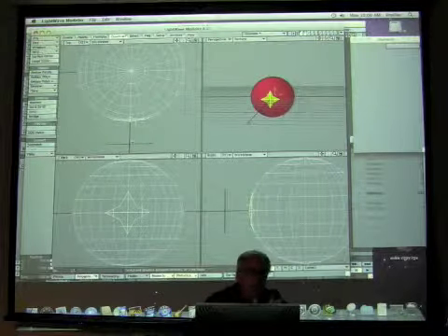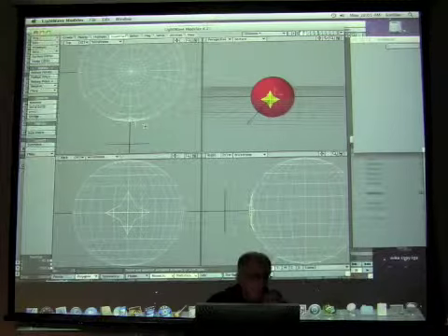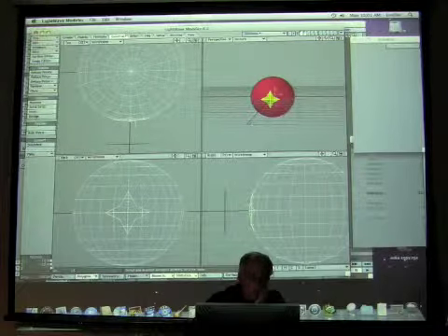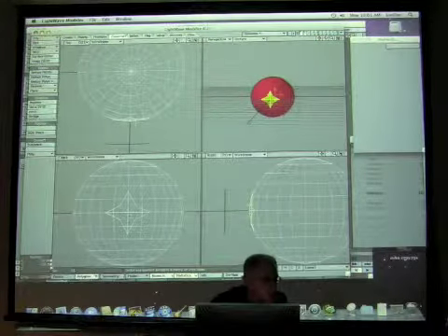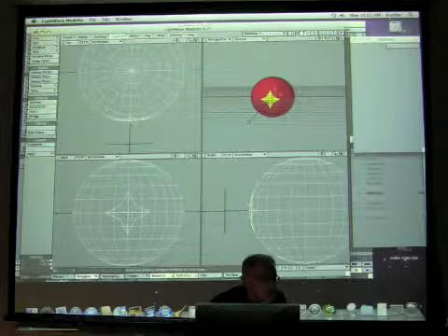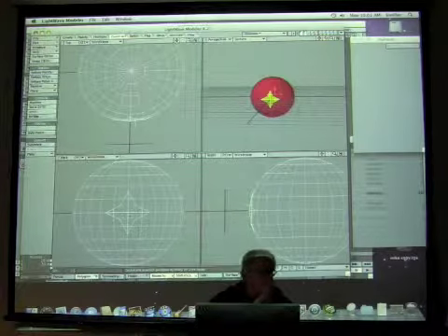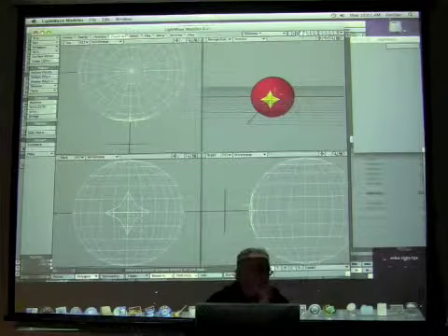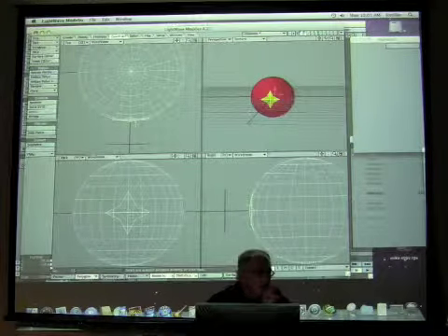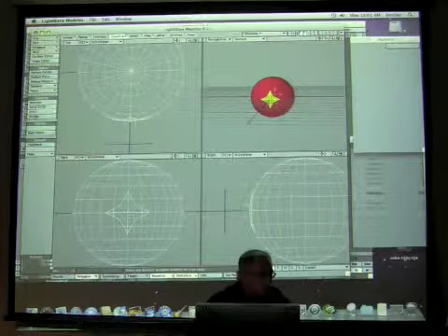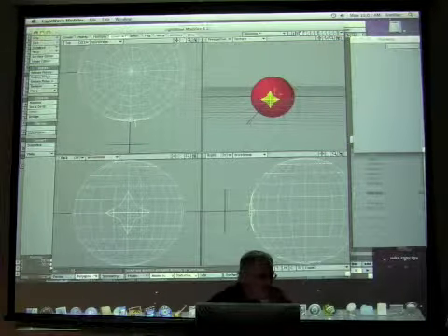But it is now, it projected that on there, and it altered the geometry. Look at all the polygons it's created. Yes? You can't partially cut. The only way you can partially cut is the other Boolean function that I showed you where you only overlap it part of the way.